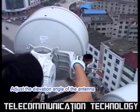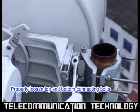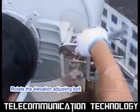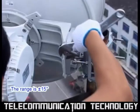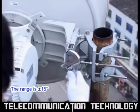3. Adjust the elevation angle of the antenna. Properly loosen top and bottom connection bolts between the antenna and the mounting bracket. Rotate the elevation adjusting bolts to adjust the antenna elevation. The range is -15 degrees to +15 degrees.